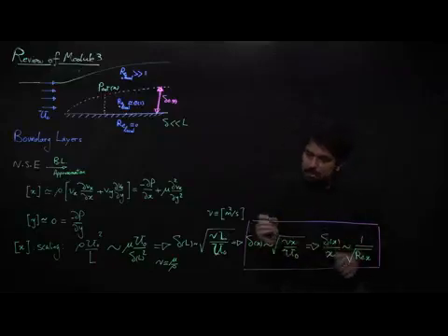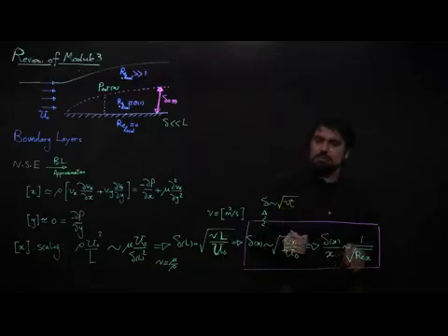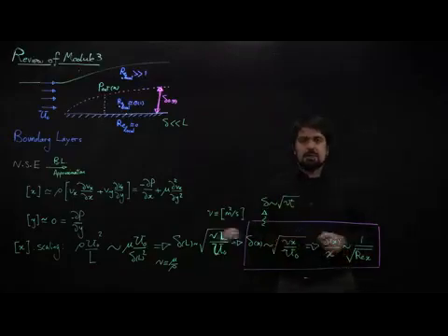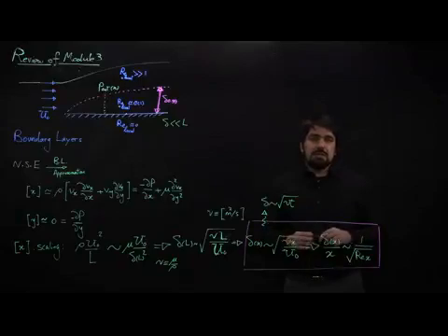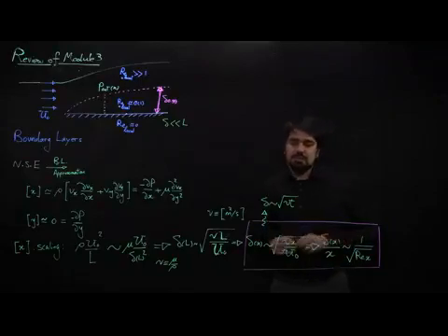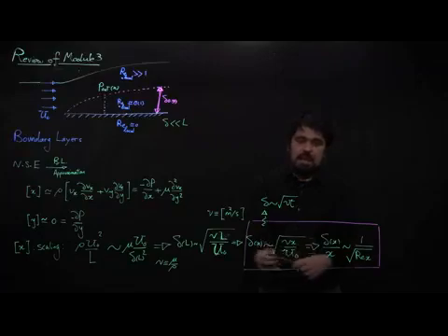And this is, again, you can go and watch the other videos. This is very much equivalent to what we had in Rayleigh problem, where delta is scaled as square root of nu times t for a transient motion of a flat plate that was stationary at time 0, and all of a sudden at t0 plus an epsilon after 0, we started moving it with a constant velocity. This is exactly the same idea in boundary layer, and the thickness, which is the length scale for diffusion of momentum or vorticity, increases in a transient problem with time. In a steady problem, it increases in a convective manner with x, and it goes as a square root of nu x over u0.